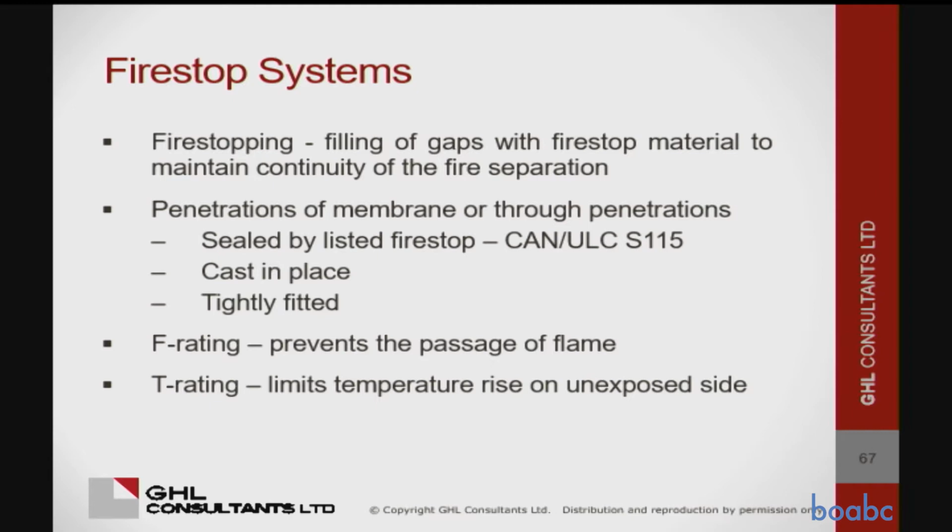So fire stopping is about filling the holes. Of course, you know that. And the code says they're either sealed by a tested fire stop system, and that's a question all the time. Architects or somebody phones from the site and they go, do I have to put fire stop caulking here? And I was like, well, I don't know, what system are you using? You don't just buy a tube of FS1 and start squirting it all over the place.